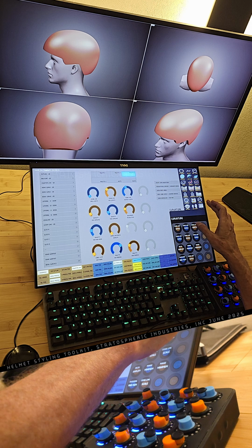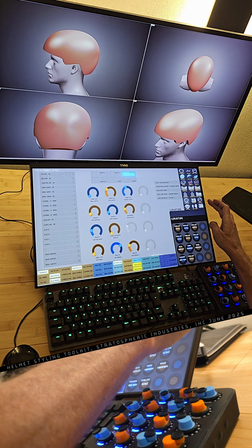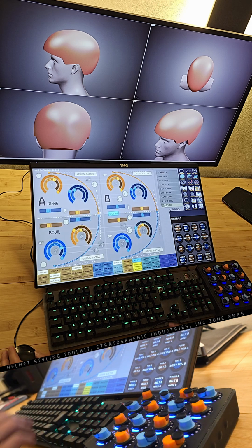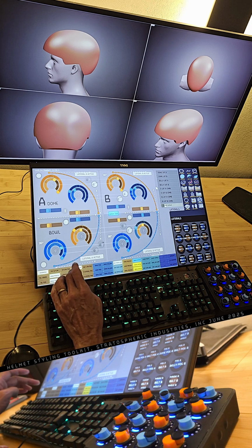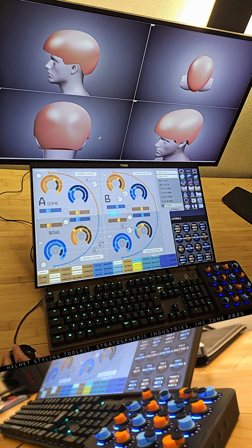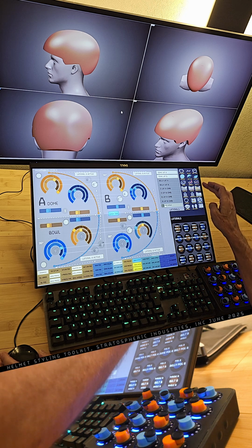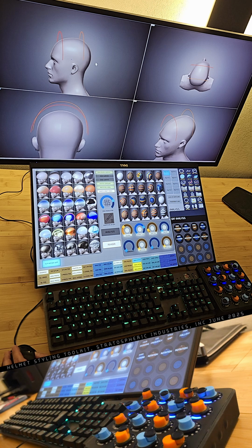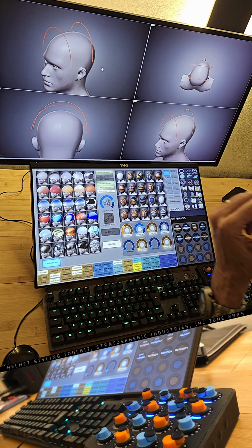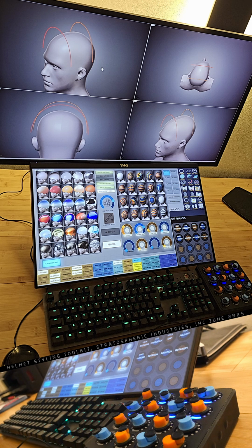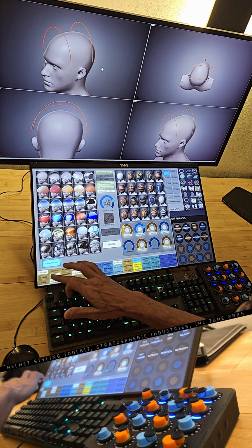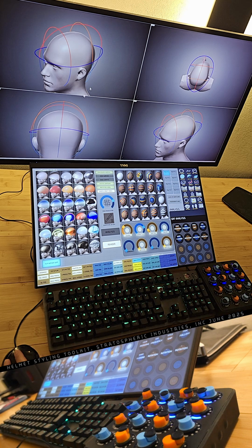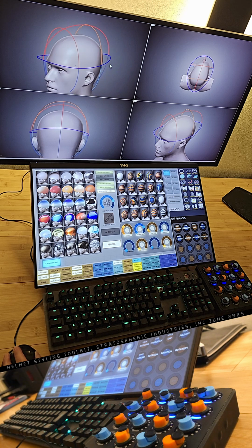Final set of settings is for the lateral shape. Before the tweak pins, the lateral curves, which are these curves right here, these curves were a lot more in play. Let's take that out for a second. These curves were controlling the shape of the helmet. This led to a little bit of conflict of definitions and some discontinuities in the surface that were difficult to control. So there's all the curves right there. These are no longer really in use. The tweak points have turned out to be the desirable solution.